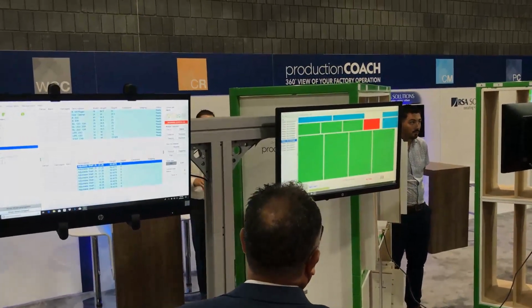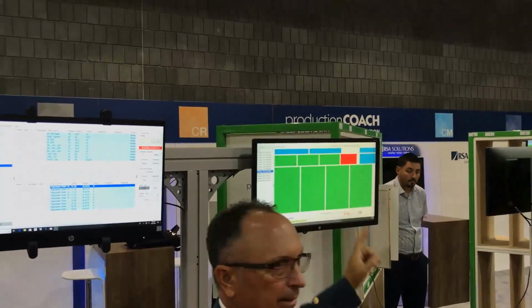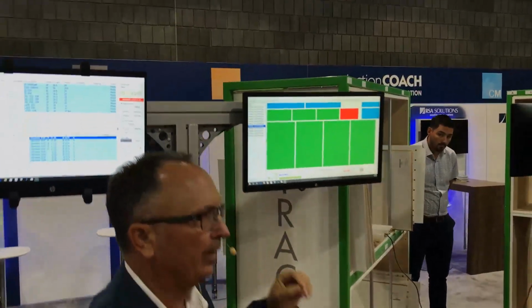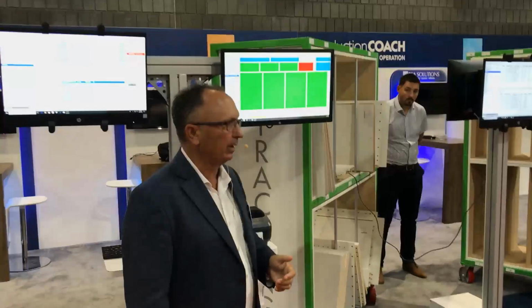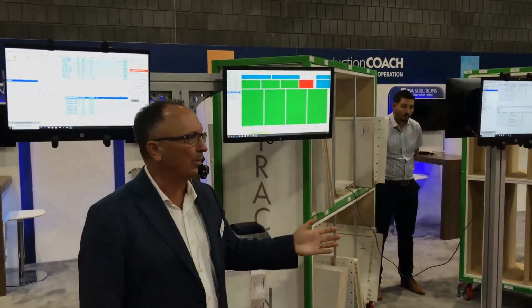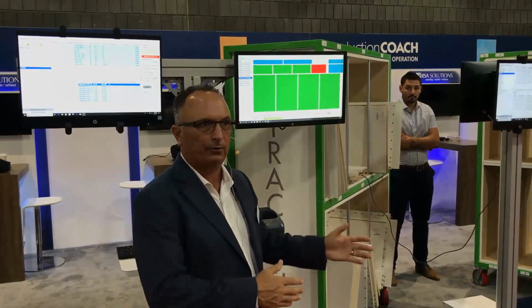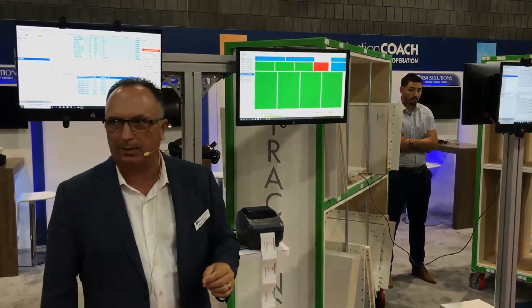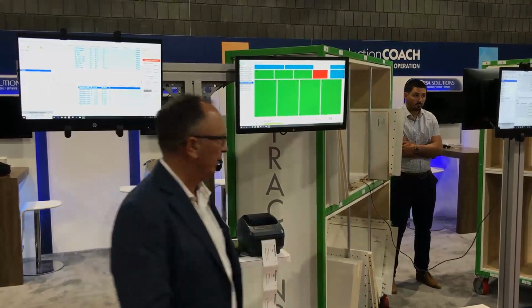There's many other things that we're actually accomplishing with Smart Labels. Number one, as parts are generating labels, we're updating them in the system. We're also displaying for the operator the grouping of parts. We can group parts in 2 different methods. For example, if our customer's next operation happened to be horizontal bore and dowel insertion, maybe we'd want to group by part type, or we might want to separate horizontals out from back, sides, or fronts. Here, we're also displaying grouping by like edge material. So we're helping the next operations downstream, whether it be edge bander or horizontal boring.